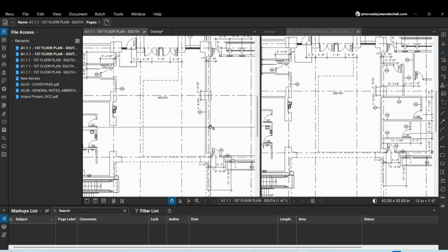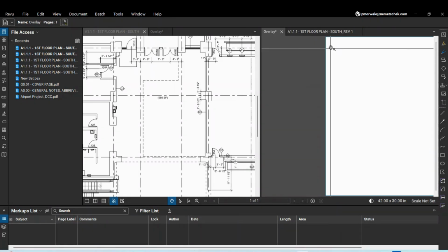When you can use the synchronized document switched off is, suppose you want to check a drawing with reference to some other document or drawing, like a specification, data sheet, or anything else you would like to check, or you have the check sheet on this side and you would like to check the drawing. In such cases, you can use that unsynchronized. So this is how you can get the overlay.